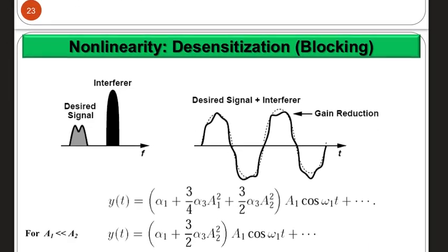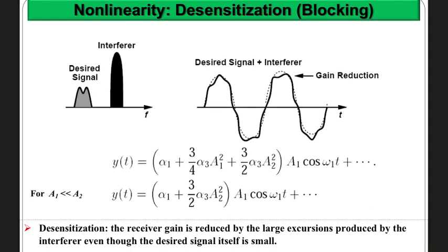Okay, good discussion. Here is another effect, which is basically an extreme case of compression, but we are not considering something from the same signal. We are considering the effect of an interferer in this case. So you have an interferer at a slightly different frequency from yours, and that interferer has a very high amplitude, and then you have your desired signal. What will happen, again assuming that your system is nonlinear, in terms of the received signal if we assume that the interferer is much larger?